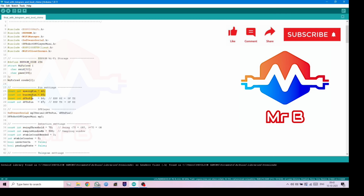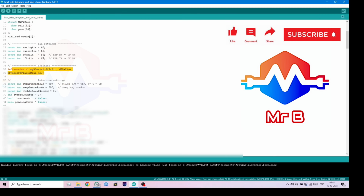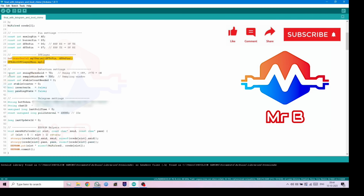Other than that, these are all the pin settings. This is the analog pin for the current sensor. This is the buzzer pin D5, and this is the D6 and D7 is the SD card of the DF player mini. There is the TX and the RX pin. This is the initialization of the DF player. Then we have got the detection settings over here. So I have marked all the different sections using comments.